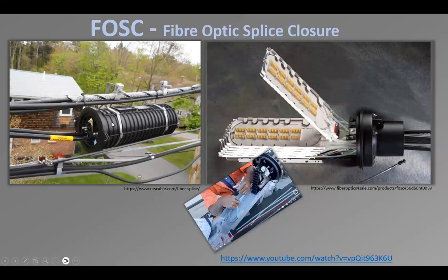You can see sometimes there could be a service van right by that spot. So this would be taken down, with enough slack of the wire, and the whole thing put in a van, which is basically a fiber optic lab on wheels, so that the fusion splicing can be done, because you need a nice, clean, and dry environment to do your job properly. Cleanliness is extremely important when dealing with optical fibers. The cladding is 125 microns thick, and if it's single mode, the core would be 9 microns thick. That core that transmits the light is quite comparable to the size of dust particles, so if a piece of dust lands on it, it can actually blind the transmission.